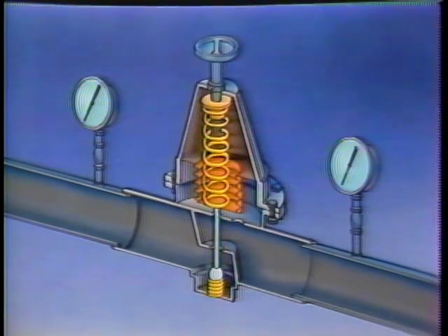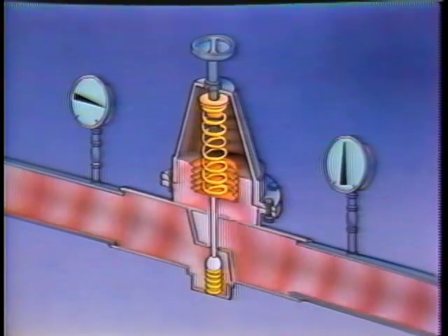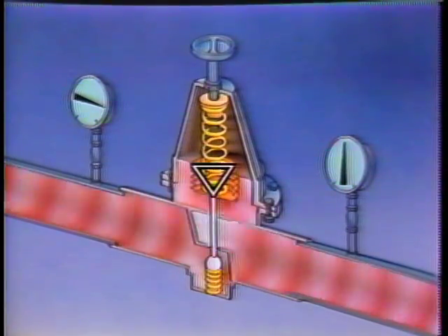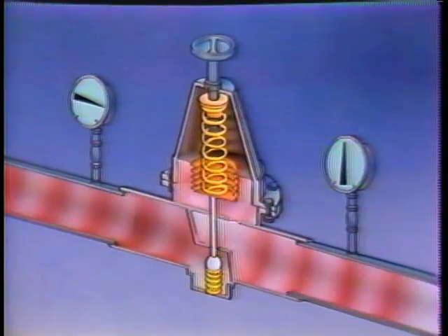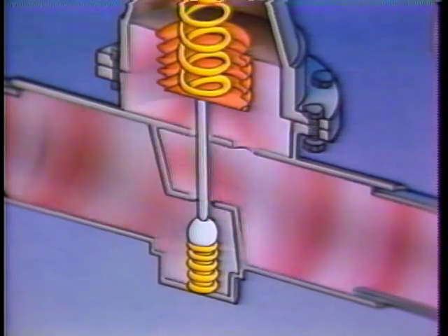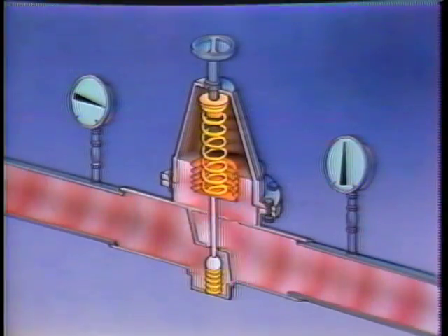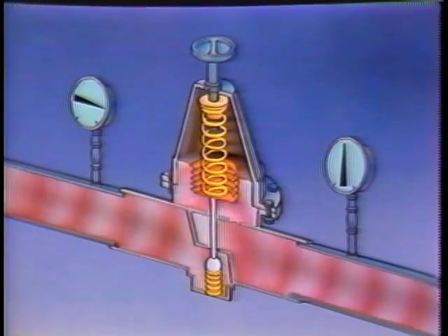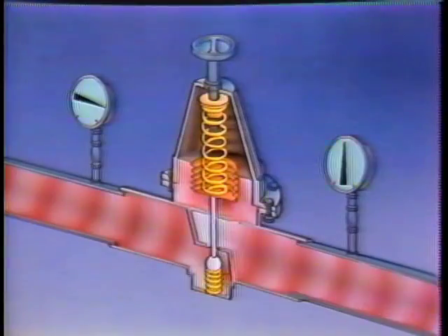When the steam passes into the outlet chamber, it contacts and compresses the bellows, restricting the orifice. The orifice size is regulated by the balance between the set point pressure above the bellows and the sampled pressure and the valve spring below. Increasing the set point pressure opens the valve further, increasing downstream pressure. If fluid usage decreases, the downstream pressure rises, compressing the bellows and throttling the valve. This reduces the outlet pressure until it again equals the set point force.